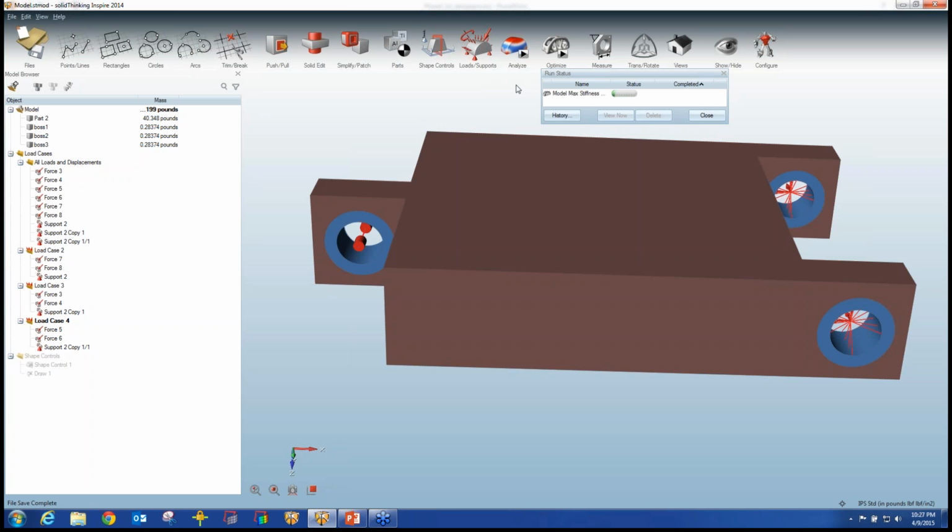So you just use the existing loads, because those are the loads that the component is going to function under, and quickly see what the stresses are going to be. And if you see the stresses are way too low, I would always go back and try running it with maybe a 20% mass target, saying, all right, you can remove 80% of the mass, so that we still have a very stiff component, but we're removing more mass.